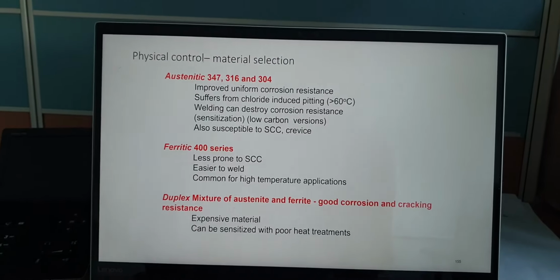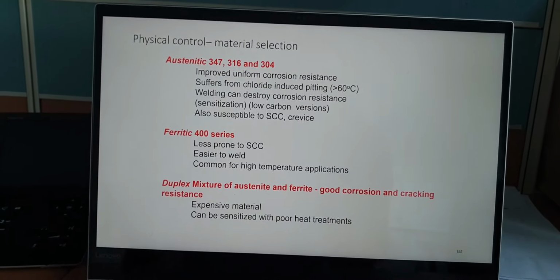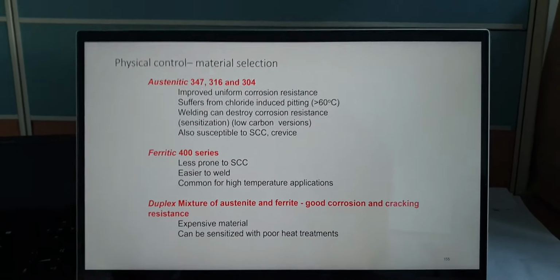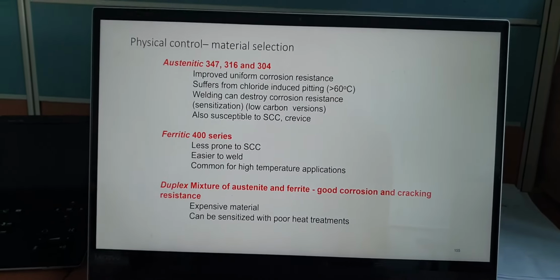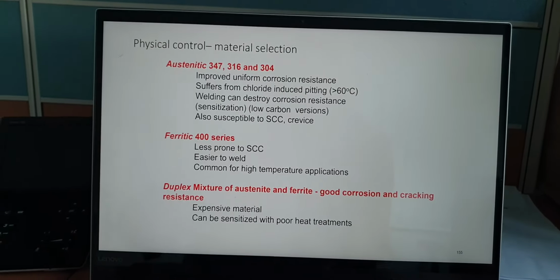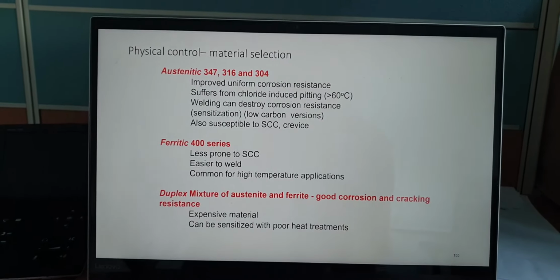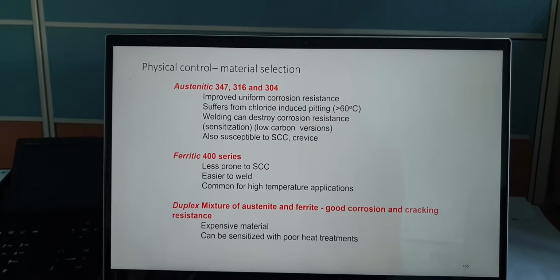If you decide at some point in your career to use stainless steel, you need to ensure that the flow inside is moving constantly, because otherwise chloride attack will take place and will basically destroy the passive film on the austenitic stainless steel.